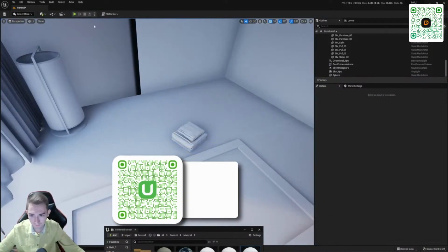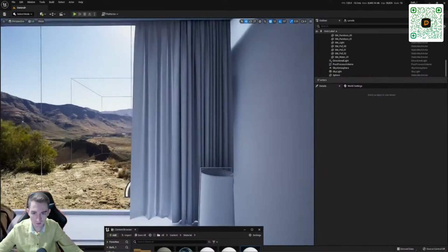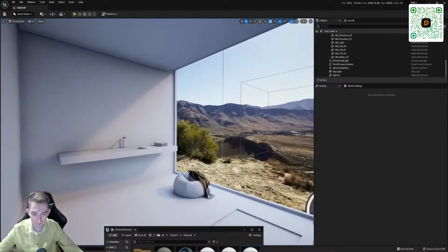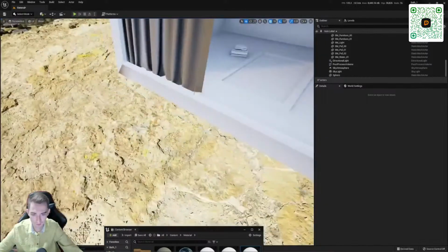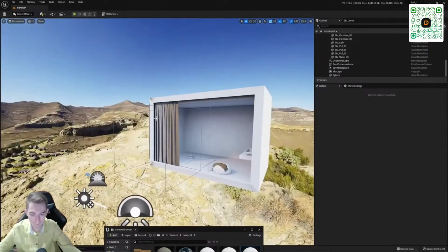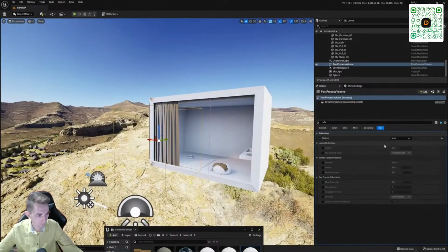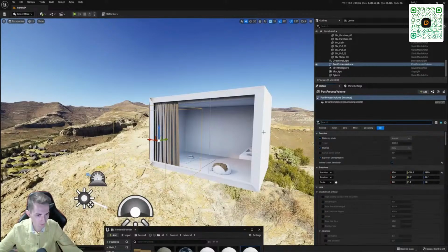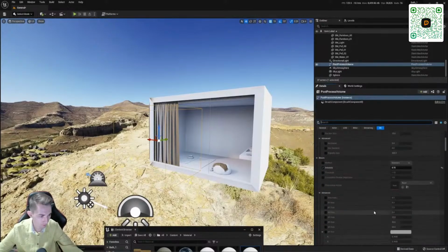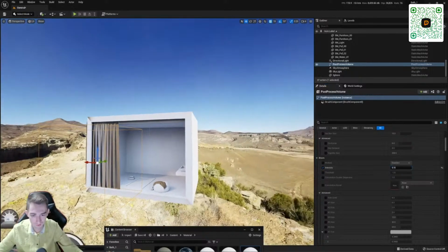So, now this is not visible, it will be visible on the materials. Just for the record, getting ahead of myself a bit. So, what else are we setting up here in the post-process? We are setting up the intensity here. There is a section Bloom and intensity here. We usually set it to 0 and only at the final stage it is possible to set, let's say, some intensity.